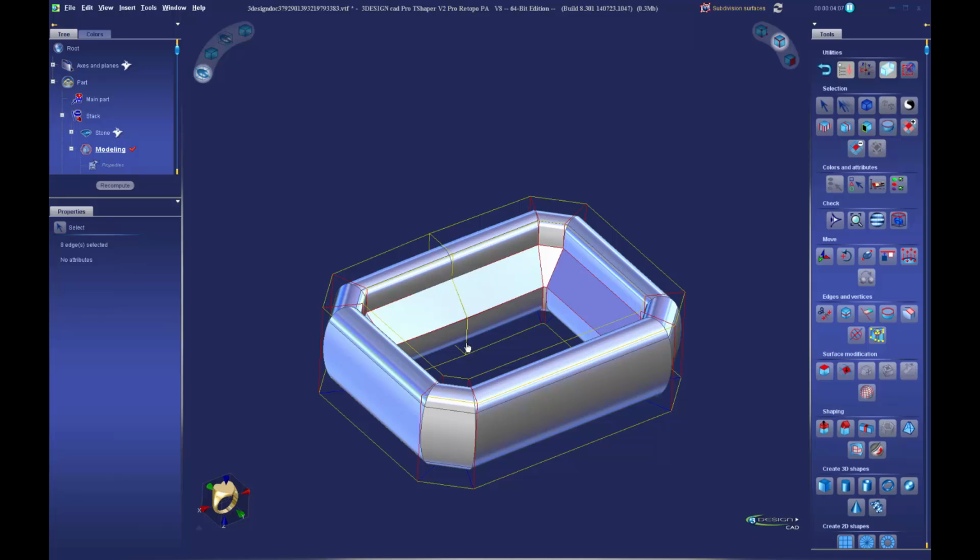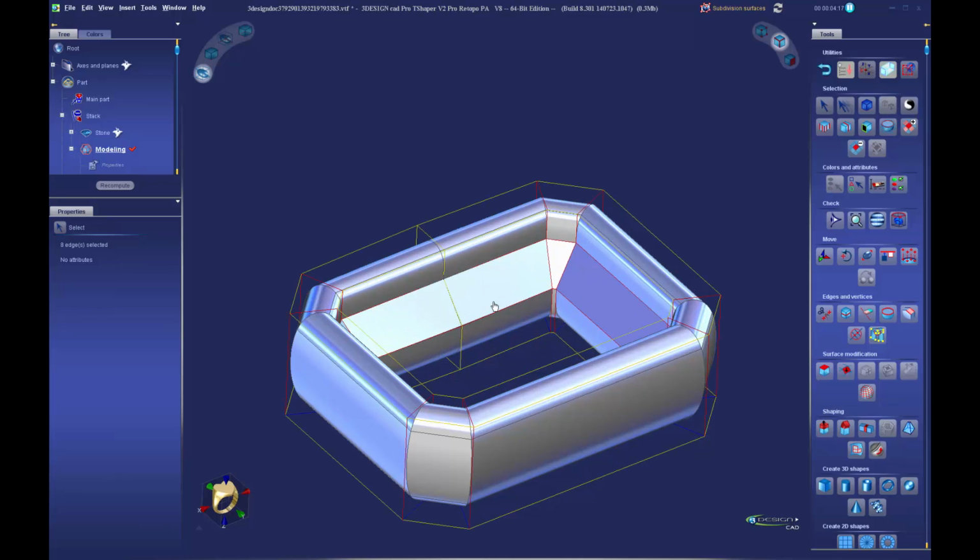We notice we have a split here on the side of our shank, or our bezel, excuse me. We have this profile here that was created because that's where our start point was on the curve. We actually want that there. We're going to leave that, but we'll put a matching one on the other side. To do that, I'm going to select one of these horizontal edges, do an edge ring, which will select all of the parallel edges around the shape, and do a split and pull. If your split and pull tool is not centered, just hit reset. Make sure we split it right down the middle and validate.